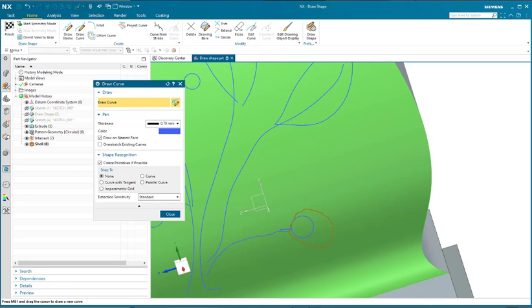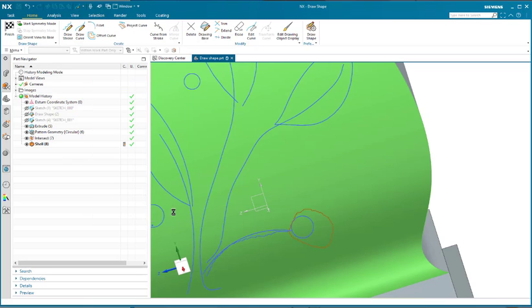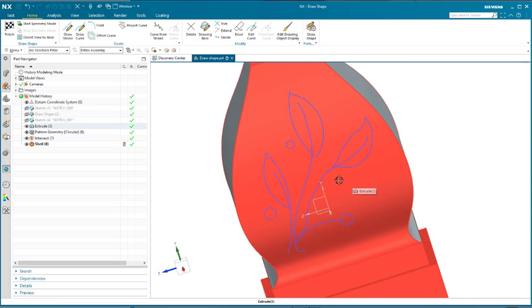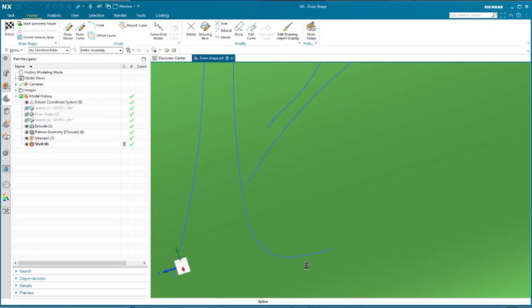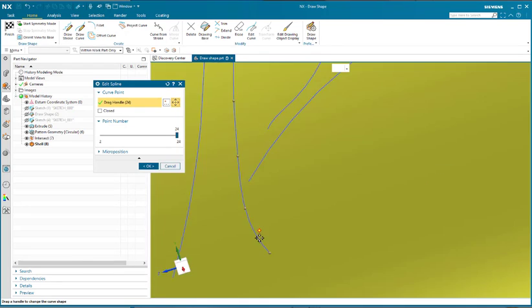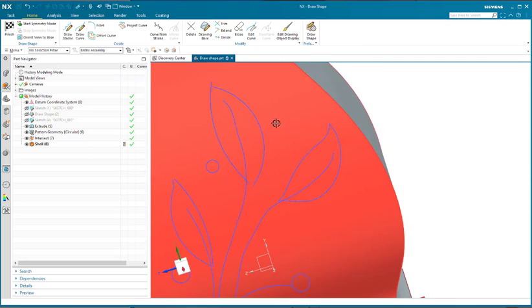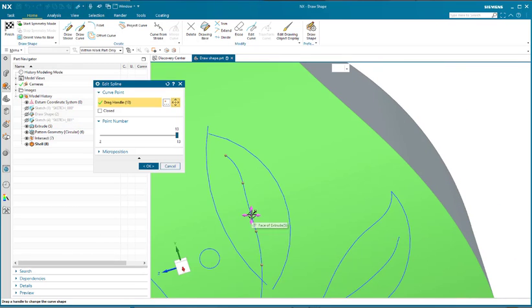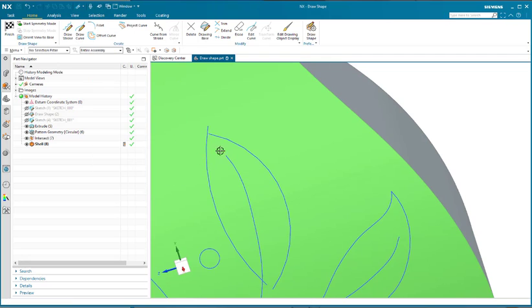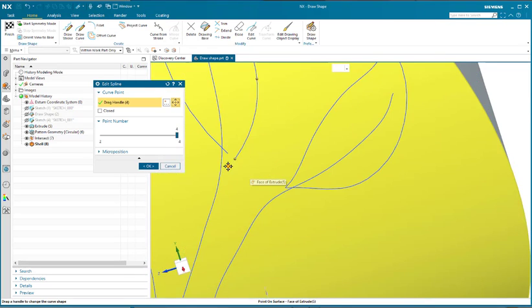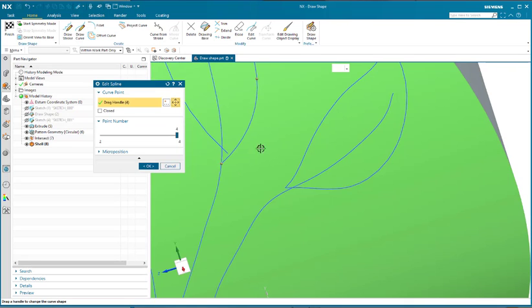And you can at some point edit the curve to put the heads to tails, or to finally close up a profile that you're going to extrude. Here I'm correcting one of the curves that went a little haywire, and if I'm not careful, I take too many points out of it, and when you take too many points out of it, you're redefining it, and with 2 points all you end up with is a straight line.